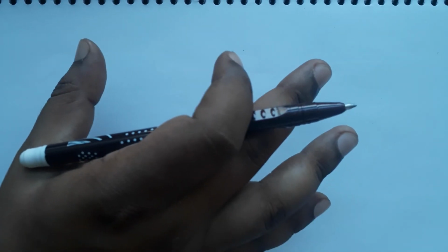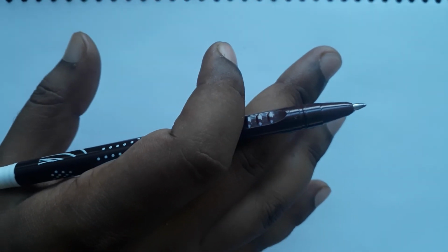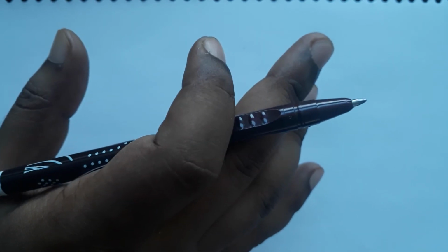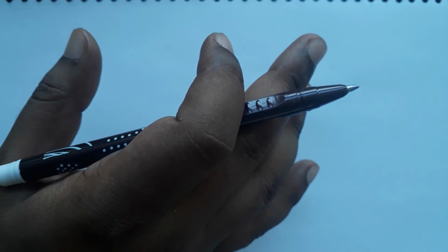The first and most important observation of fatigue is that the fatigue starts from the surface. Although this is not completely true, for high cycle fatigue and low cycle fatigue this is the truth, that the crack starts in case of fatigue from the surface. And this is why when we do fatigue testing, we make the specimen mirror polished. We do not want any roughness on the specimen. For example, I have tested the same material.